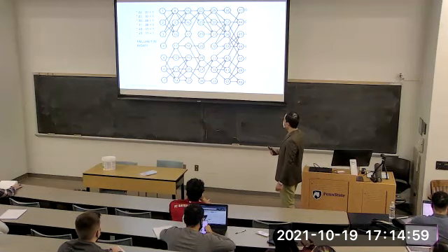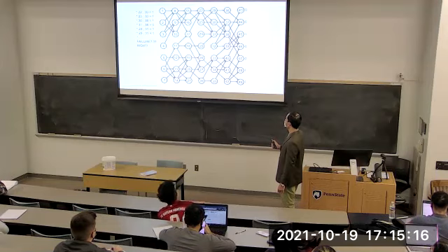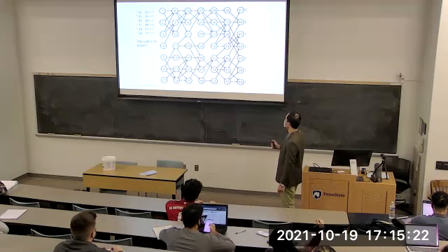Next time, 30 to 38, this one. So this was tested, this was tested. These are all both 1. And now the trainee is trying to figure out whether this one is the faulty component or not. So the next move is 30 to 38, which is also 1.